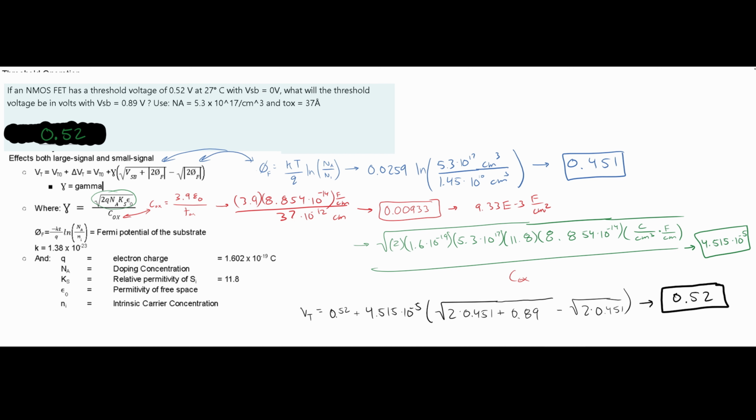So this is equal to the thermal voltage, so kT over q. There are constant numbers here. The only thing not constant is our specific temperature, but that's at 27 degrees Celsius, which is pretty common. You can go onto a website that I'll have in the description below the like button for a thermal voltage calculator, and it'll calculate the k times T divided by q. And you're going to get something that looks like this.